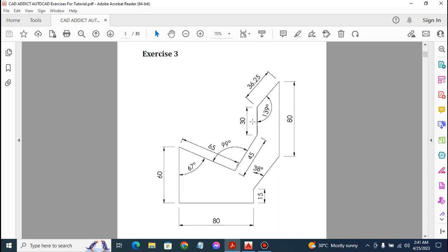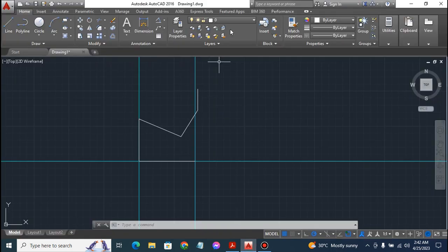So when you subtract this 139 from it, the angle that is supposed to be surrounded out of these angles is 41 degrees. In order to do that, we have to project a construction line at 49 degrees. So let's go back to CAD. Go back to our construction layer, go to your layers toolbar, select the drop down menu of the layer, then click on construct one.